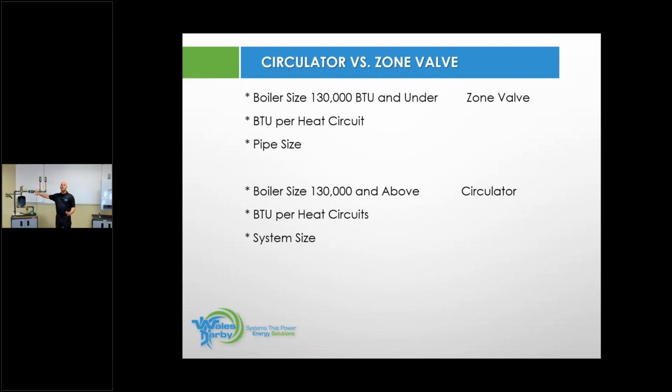Well, they did. But if you look deeper into the manual, they gave you that because they want it piped primary, secondary. And yes, this has the ability to move the water across that cast iron boiler heat exchanger at 2 to 3 feet of head at 25, 26, 27 GPM, and it will handle the boiler. But then you would have to address the system side separately. So keep that in mind. This is just food for thought.